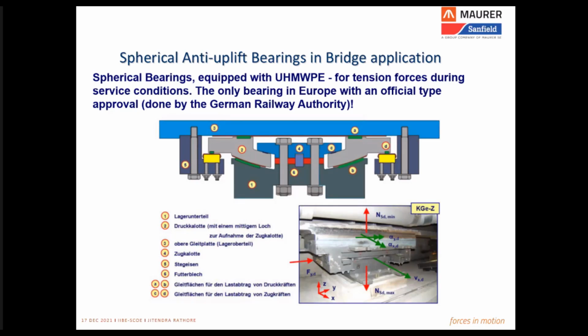But when it becomes a service uplift, it means it is a day-to-day affair. By day-to-day affair, I mean it may be happening every now and then in the bridge due to live load, or maybe due to wind, or any other reason. And it may be happening 10 times in a day or maybe 1,000 times in a year. Then the design of the bearing and the approach of the design changes upside down. We have to take into consideration the fatigue design aspects, and the overall design philosophy of the bearing changes, and the bearing system somehow looks like this.